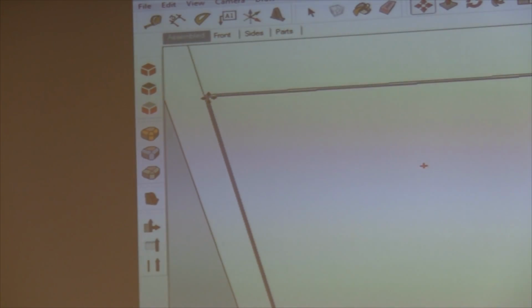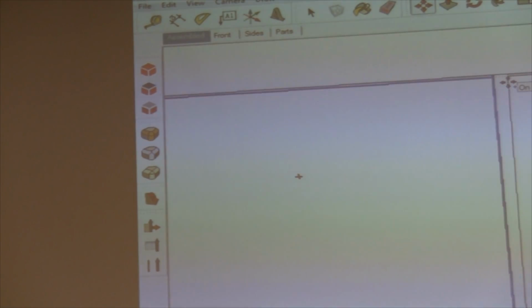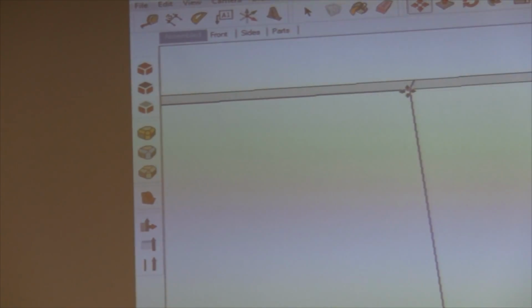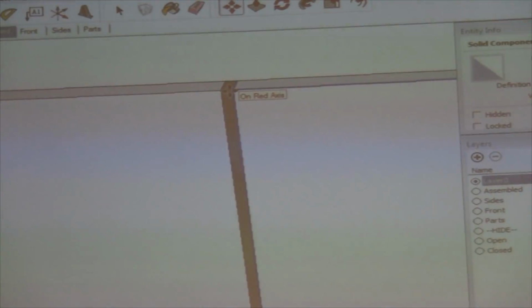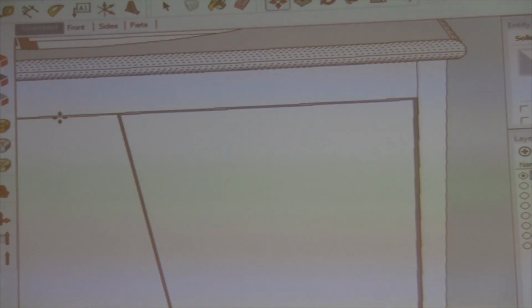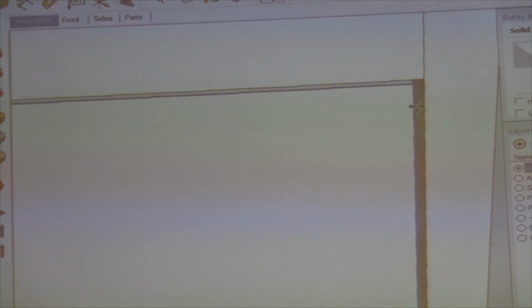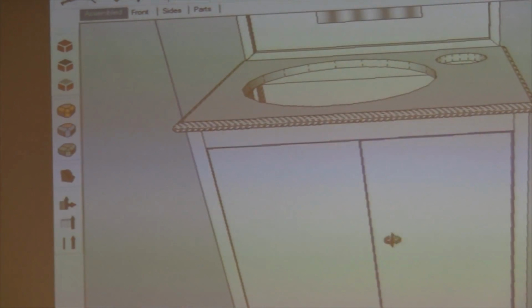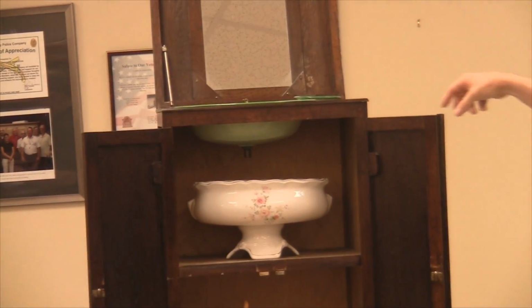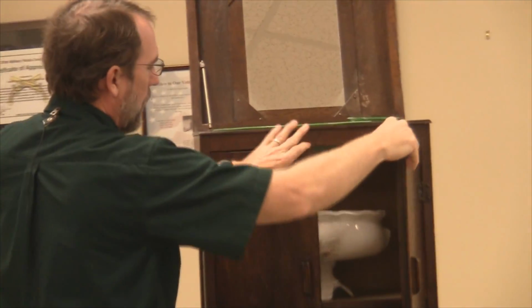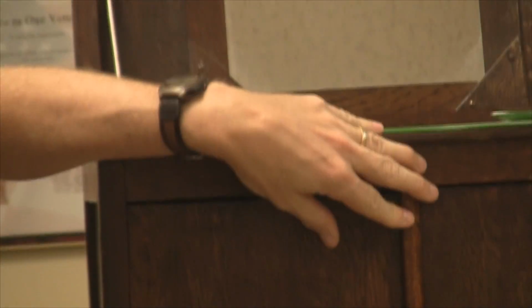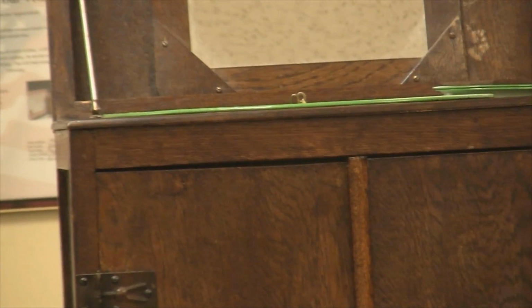And I'm going to replicate this door now over to here and do exactly the same thing. Move that a 1/16 of an inch. And now my door is spaced in the way it should be. My two doors. So the only thing that remains with the doors is that you can see on this one, there is a lip that is put on one of the doors, so one door closes on top of the other and it hides the seam. So we're going to build that piece and we're going to put it onto one of the doors.